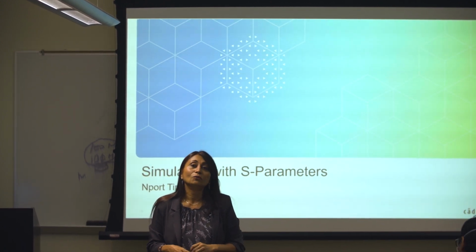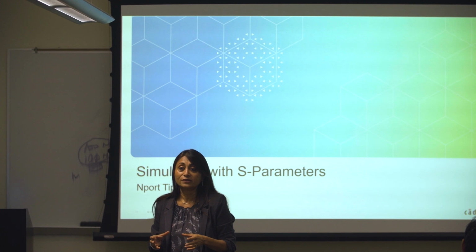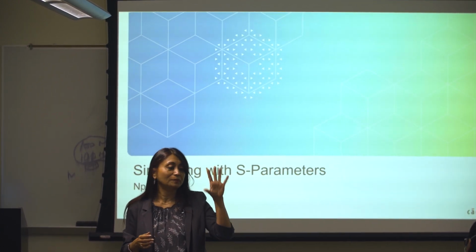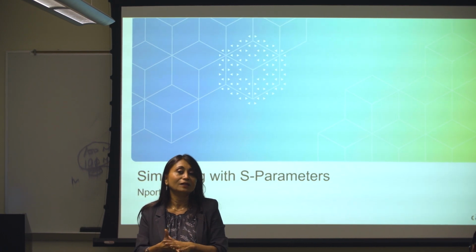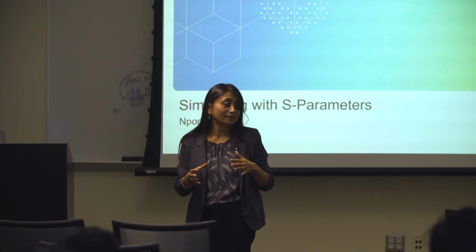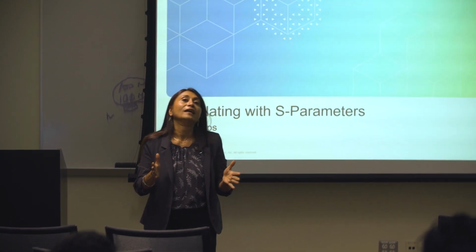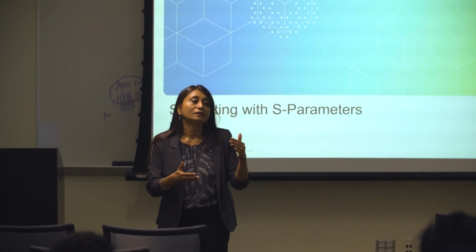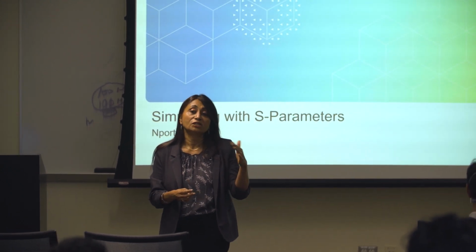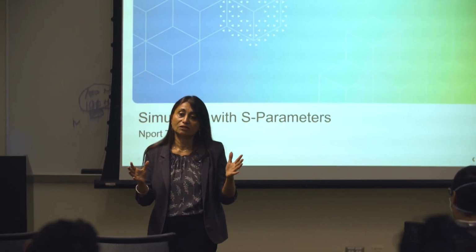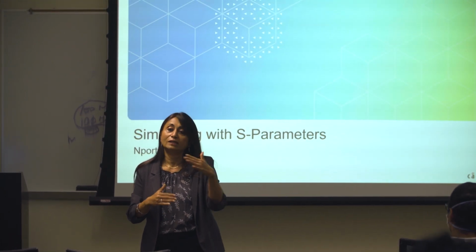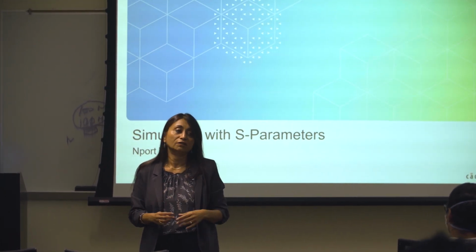And if you want to look at noise contributors, run PNoise or HB noise and go to PSS noise summary. I don't know if everyone knows, but then you can do spot noise or integrated noise over a certain range, and then you can say, I want my top 100 or top 20 contributors. It could be just resistors, it could be all devices, it could be just transistors, doesn't matter. You can choose that, then you can get your top 20, top 50 contributors.